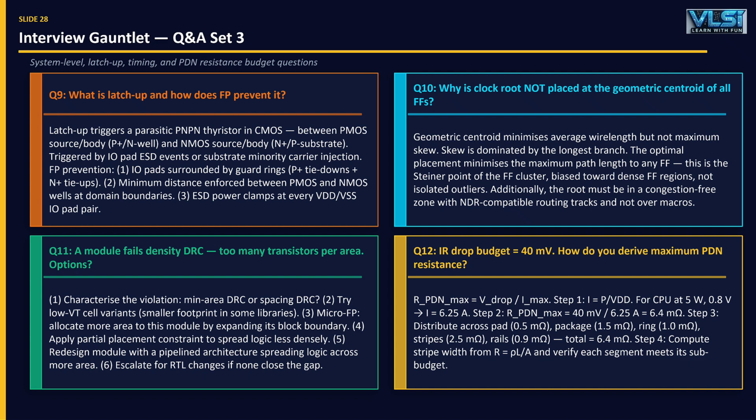Now we move to system level thinking. This is where you think beyond just design. Think long term. Temperature increases resistance, leakage increases, electromigration worsens, hotspots appear, so you distribute power blocks. Avoid clustering. Consider worst case scenarios, not just typical cases. Also consider latch up, unwanted current paths, prevented by spacing and guard structures. So this is designing for reality, not ideal conditions.